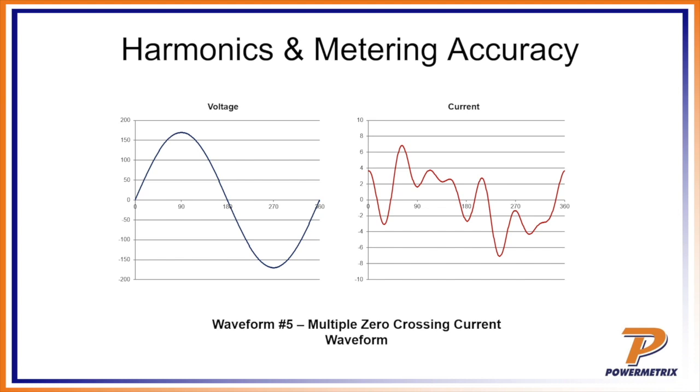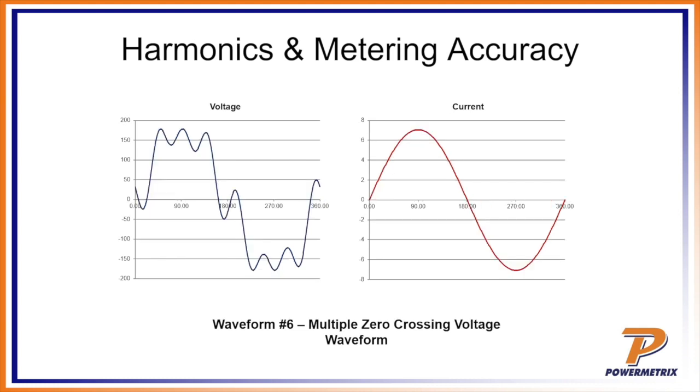That's a problem because that would really confuse the clock inside of those meters. It's not 60 hertz anymore. It's going to be a much higher harmonic than that. And so the meter would just sort of go nuts and give really bad registration. So that was a very important waveform that needed to be rectified, and the ANSI committee added that to the standard so it could be tested for.